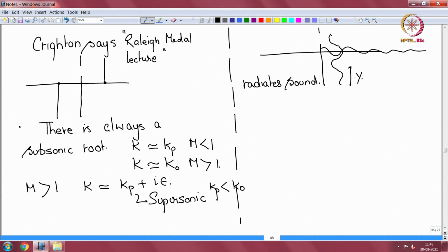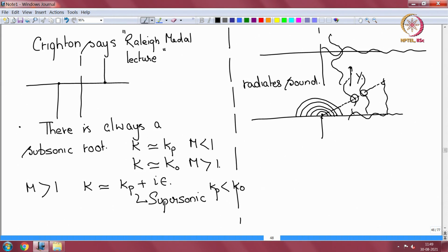It's a little counterintuitive. However, if this is my plate and this is my line forcing, it may be increasing this way. But as this happens to be the origin of the entire vibration and sound, and the propagating wave along the plate is decreasing, a little to the right the vibration has decreased and the sound field grows. A little further to the right the vibration is further decreased and the sound field grows. But if you look at a radial line originating from the forcing, you will see that the sound field is decreasing.